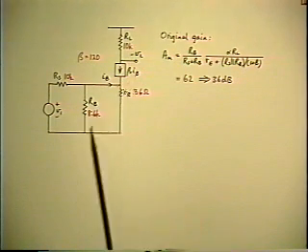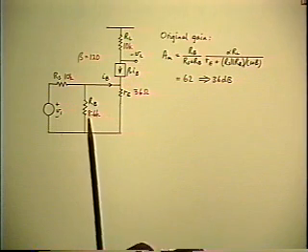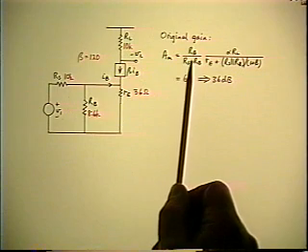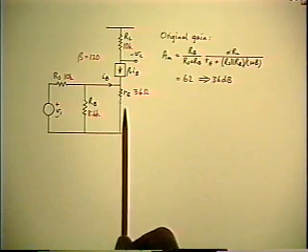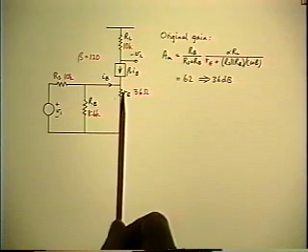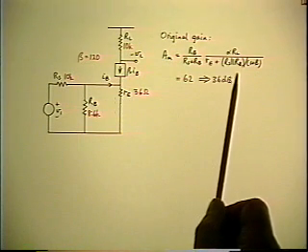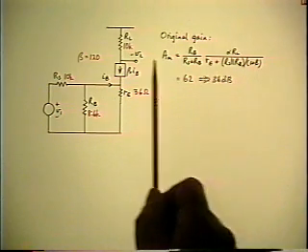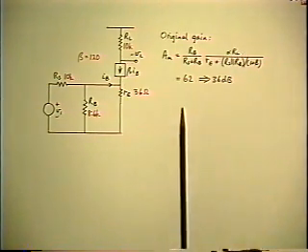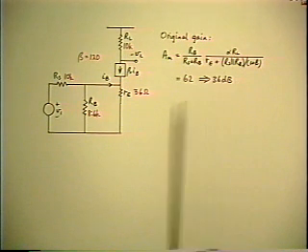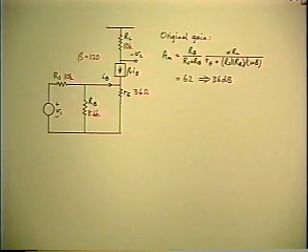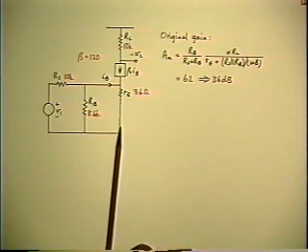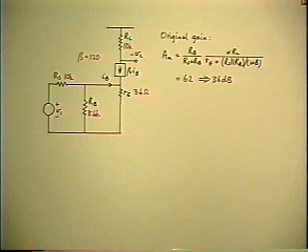And once again, you could go through the mental circuit reduction, eliminate one loop by Thevenin, which gives you the Thevenin divider in front, reflect the base resistance into the emitter. Thevenin voltage is applied right across the combination. So the denominator gives you the emitter current multiplied by alpha multiplied by RL. The result is 62 or 36 dB.